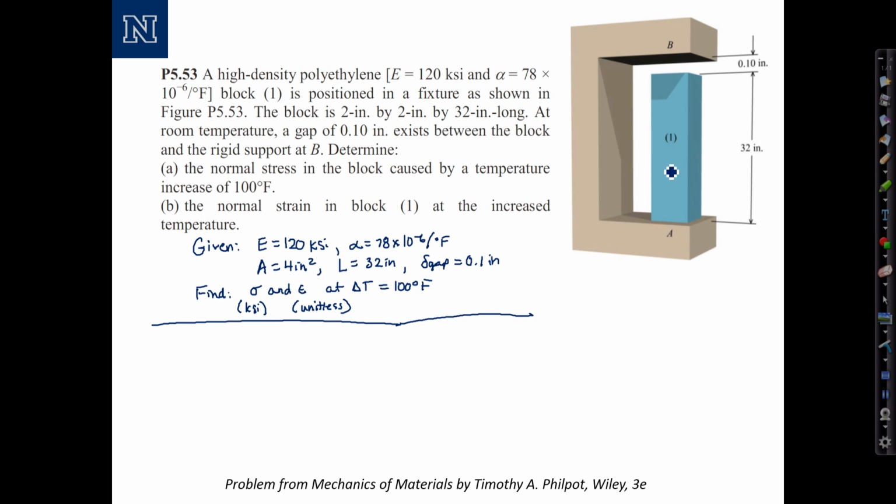Let's consider what happens if we apply a temperature increase. We apply a temperature increase, the block will expand and continue to expand until it closes this gap. As it closes the gap, we expect these rigid supports to press upon the block, and so the block will become in compression, and the greater the temperature increase, the greater the compression force that would be observed in the block.